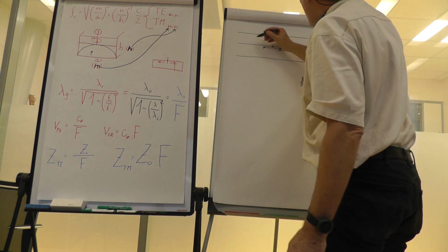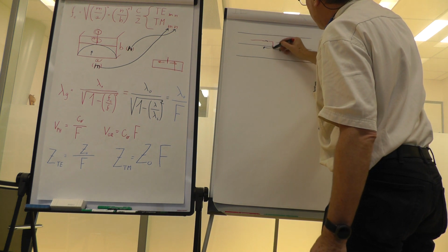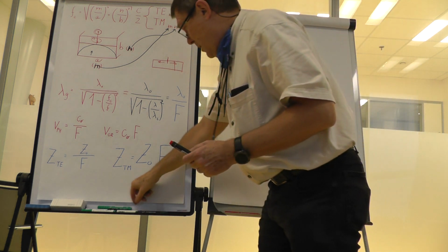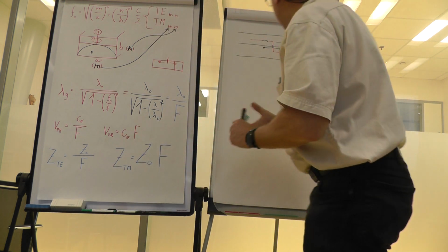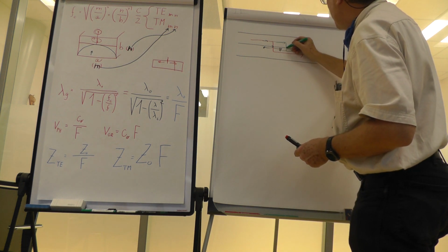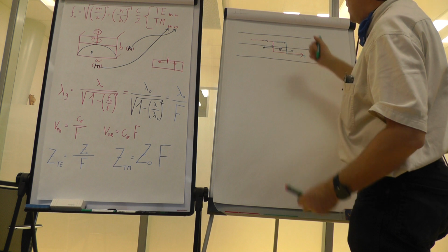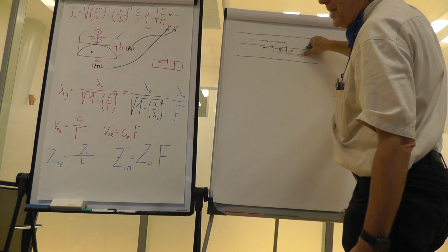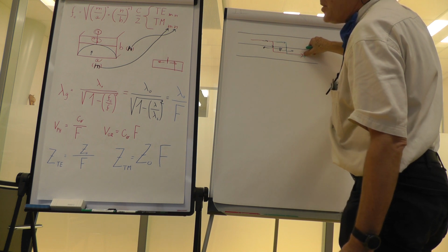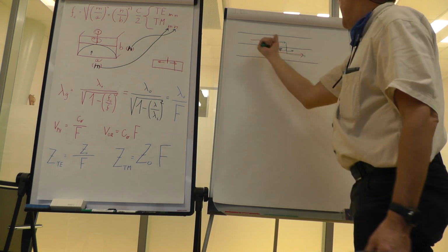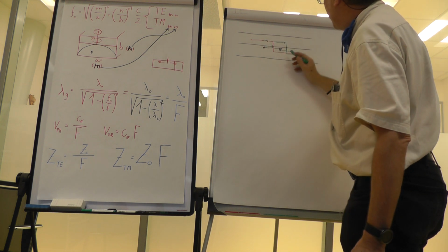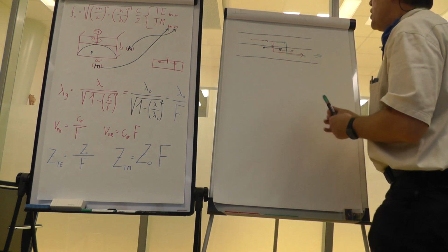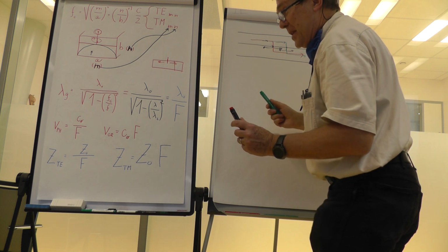Just look, if the wave propagates this way, then this is the path of the first signal, and this is the path of the second signal through the second hole. Now, you can see that in this direction, both waves have the same length and therefore phase. So those two waves radiated by the small holes add up, and we have a result in this direction, which is not the case in the opposite direction.